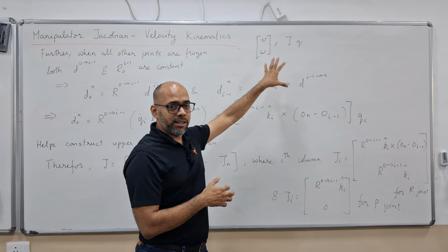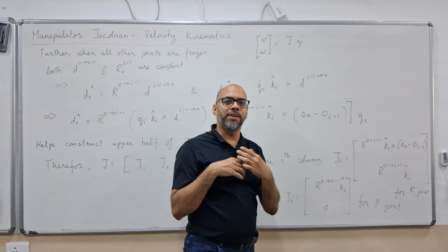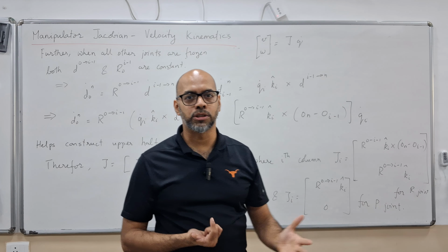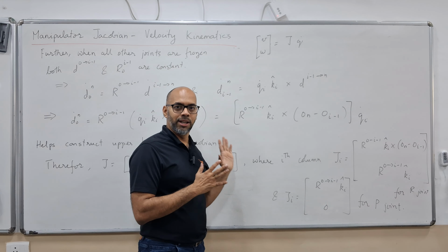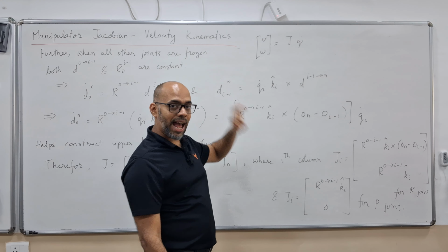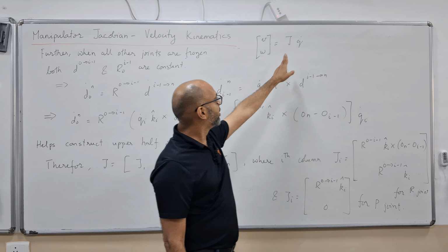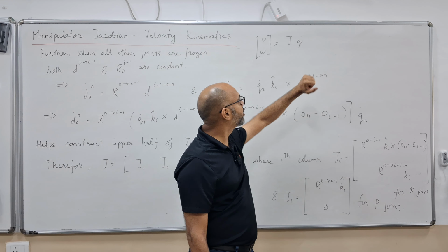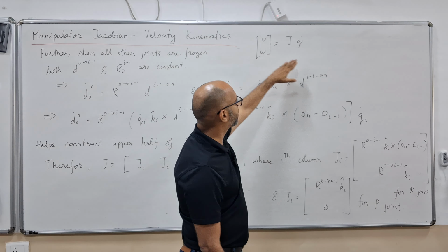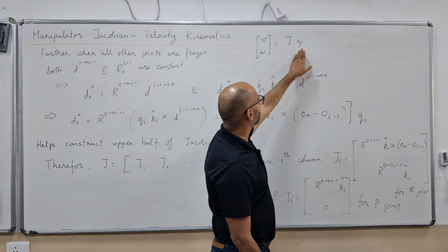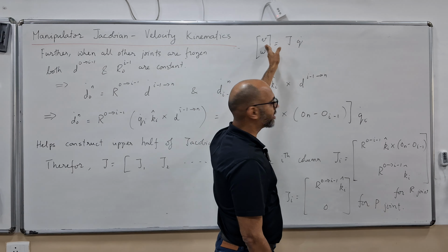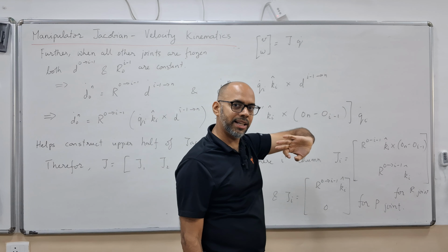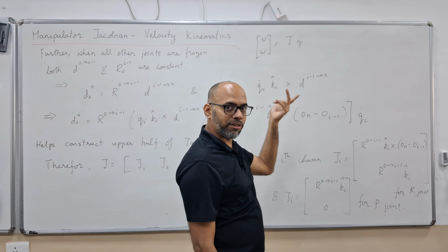But using the Jacobian, you can very quickly determine how close you are to singularities by just looking at the rank of the Jacobian matrix. In fact, at the singularities, the rank drops, which means when you look at this expression, there are some motions at the joint and nothing is happening at the end effector along certain directions, or it could be the other way around, right?